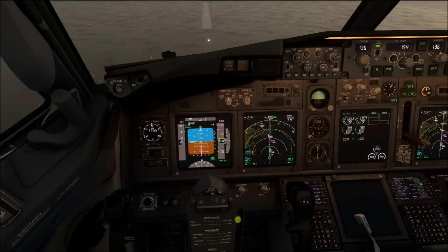So, we are going to do the static run-up just prior to takeoff, and we will turn directly into the takeoff procedure from this. Alright. The requirement for a static run-up prior to takeoff must be coordinated with air traffic control, especially at high-intensity runway operations airports, and communicated in advance of accepting a line-up clearance to ensure arriving traffic is not accepted.